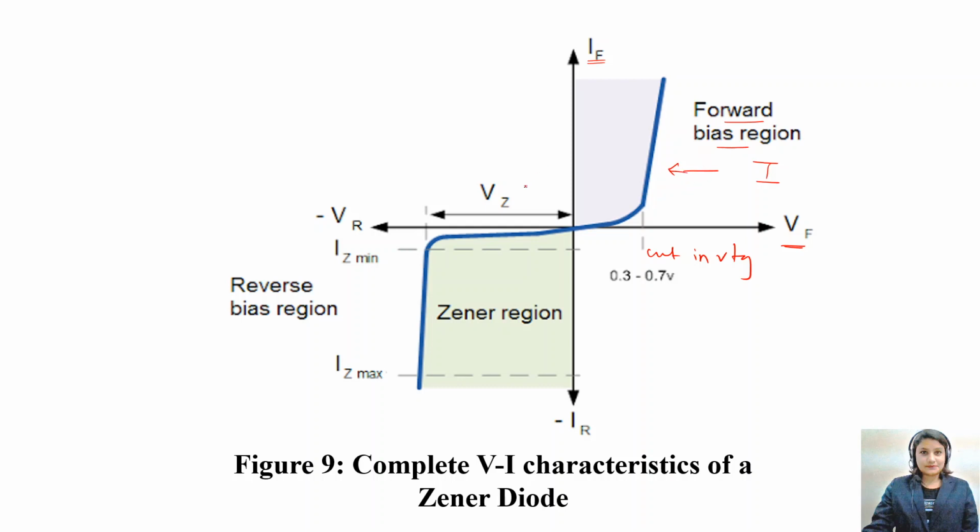Right? So if we make diode to be reverse bias, you apply the reverse voltage. Though the current is flowing in the reverse direction and that is sharply and suddenly flowing, this voltage in the Zener, it remains constant. Right? And you can use this property as voltage regulator.